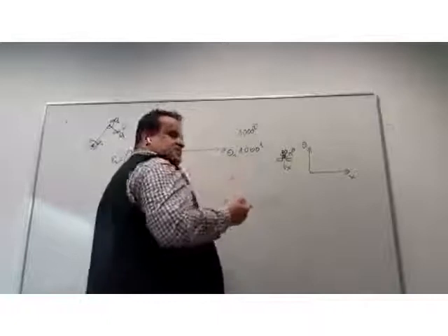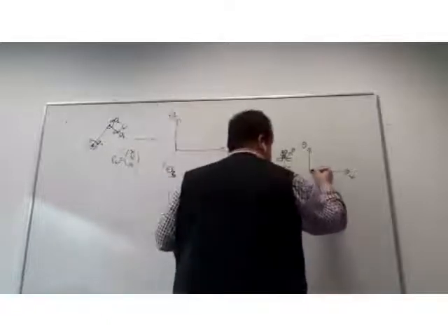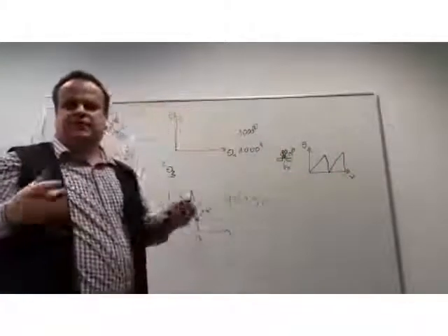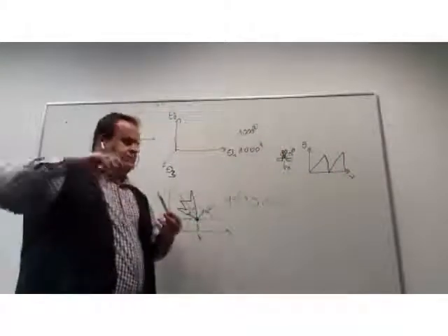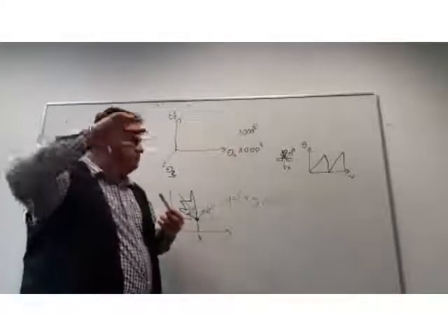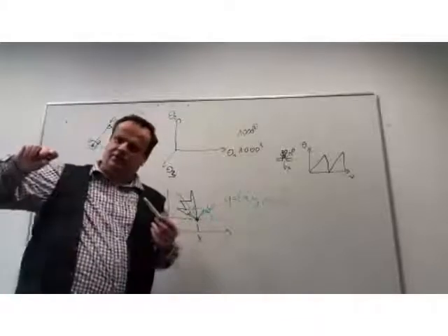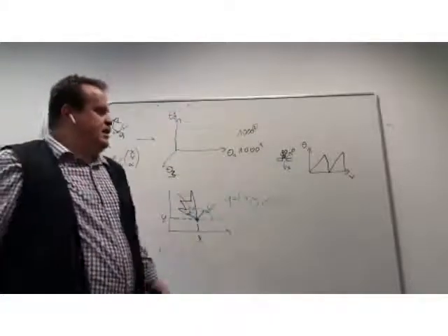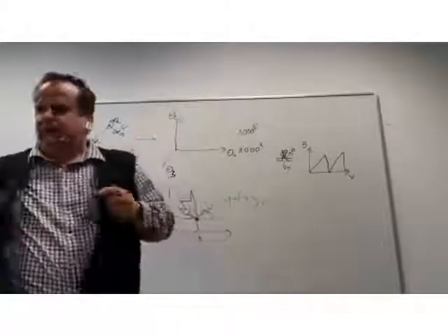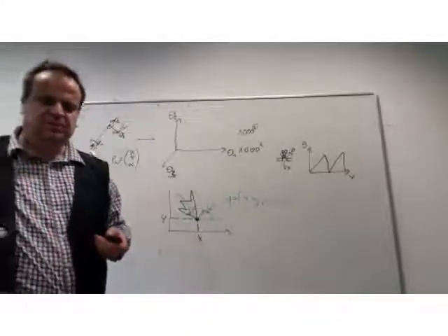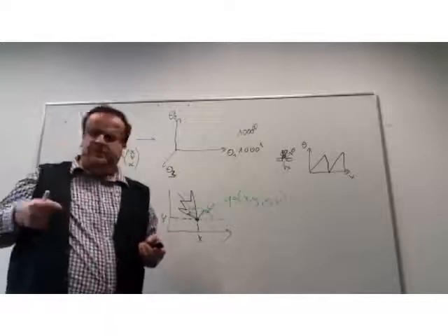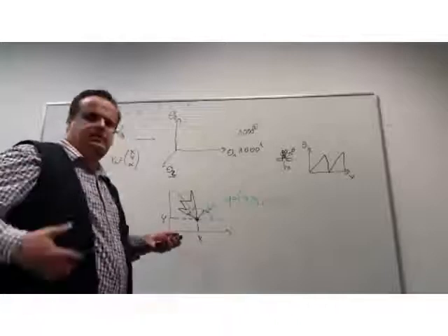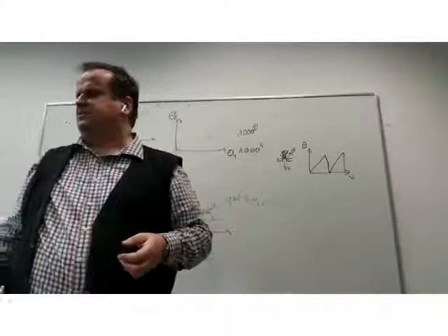But if you look at possible points in the configuration space, you will see that x and theta are coupled. For a specific theta, depending on how I turn the screw, I get different depths in the nut. So I have dependencies. If I don't choose the minimum number of parameters, then I get a dependency between parameters, and I'm wasting dimensionality to represent my system.